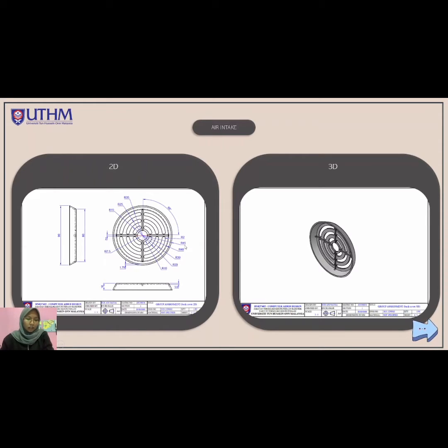After that, I move the 40 millimeter circle to the top of the 45 millimeter circle with a length of 10 millimeters. Using the loft command, I connect these two circles and it becomes like this. And I use solid editing shell and remove the bottom face and set the offset to 1.79, and it will become like this.